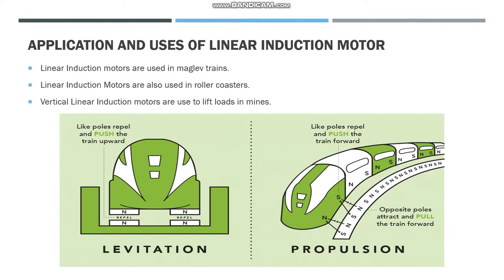About the applications of linear induction motors, the main one is the magnetic levitation train. Here the whole track of the train is the rotor of the motor, made up of permanent magnets, while the train is the stator or the sliding part, which is made up of coils.